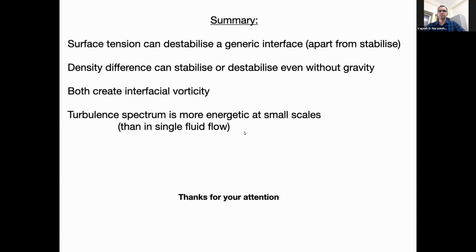Palash Kumar says, is the zero viscosity case singular? Palash, in this case, the zero viscosity case is not really singular because typically singular perturbations come when you have, let's say, a wall. Typically, you need a singular layer or a boundary layer which creates this singularity. And in our case, that thing is not there because vorticity gets created directly on the interface, and it's just a simple case of Kelvin-Helmholtz. So just like the normal Kelvin-Helmholtz, if you calculate it for an inviscid flow, you will get a pretty reasonable answer for a viscous flow. The same thing is going on here, so it's not acting as a singular perturbation. As I keep reducing the Reynolds number, viscosity will dissipate my instability a little bit. That's about it.